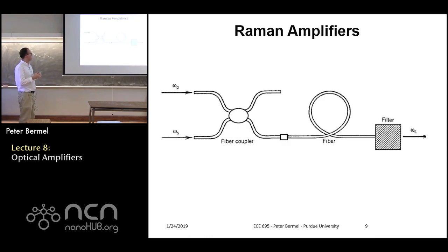Okay, so what is a Raman amplifier? Simply speaking, it's a mechanism where you can have a pump frequency that will boost a signal. So in other words, you have some signal coming in, and you have this pump frequency, and this pump frequency interacts with the signal to amplify it to a significant extent. And then it can come out as your new signal.